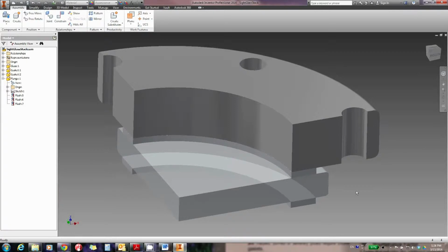Now, for this simulation, the flange is actually immaterial. It's just here so that you can see what the whole thing would look like, but the actual loads are imposed on the gaskets themselves. The cut surfaces have been rigged with boundary conditions that create a symmetric behavior so that the whole thing would behave like a complete circle rather than a quarter slice.